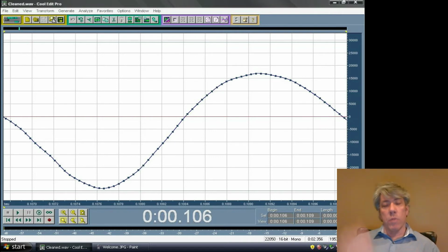So 0 to 1023 is the range of numbers. And most of the time, that's adequate. I mean, think about it. What if you just wanted to measure a change from a range of temperatures from 0 to 100 degrees Fahrenheit? Well, if you can measure 1,024 different temperatures, you can break that range.